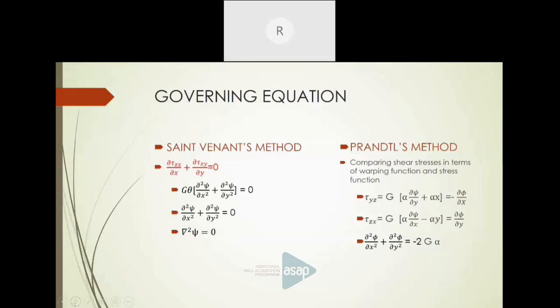You can see here the boundary conditions from the second surface, means the region R, the R surface. There we know that we have no forces, we only have one moment, and that is Mz. All the forces are 0 because we are concerned about torsion. Torsion is due to the twisting moment. So Px, the force along x direction, is 0, Py is 0, Pz is 0, and about the moments, Mx and My are 0. Why? Because Mx and My are concerned with bending. Now we are concerned with torsion, so only Mz exists. And what is Mz? Mz is the twisting moment, which is equal to T itself. T is the twisting moment, or torque.